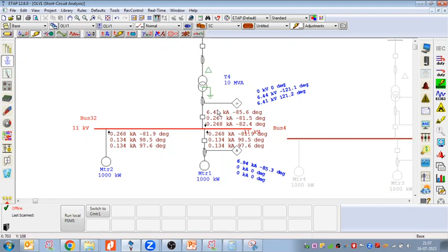Only one line fault happened, right? So while 6.41 kiloampere is flowing, in the remaining two lines only about 200 ampere is flowing, right? At the same time, on the voltage impact, the faulty phase has 0 kilovolt, but on the Y and B phases, supposing R phase is faulty, the voltage remains the same as phase voltage, 6.4 kV and 6.4 kV.